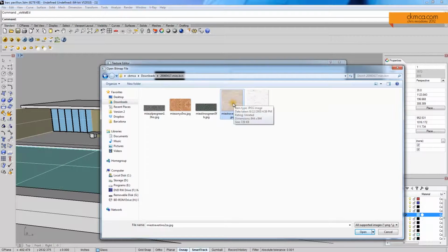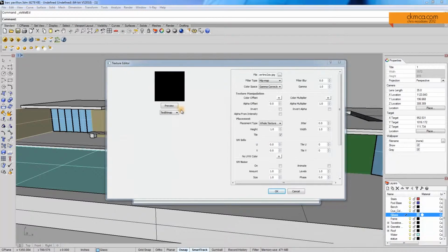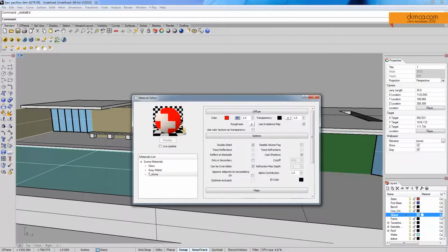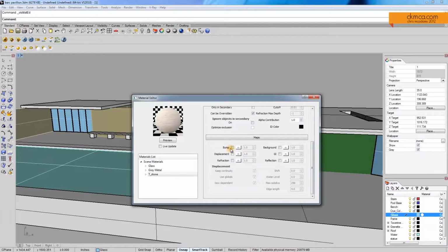So this is the diffuse map, and then we have a bump map. With the diffuse map, I'm going to pull it in, and we can see it's kind of a tannish stone floor, like we'd expect. And now when I preview this material, it's no longer red. We're using this map. The next thing we want to do is to put in the bump map part of it. The stone is not perfectly smooth and flat. It has some flakes to it. It has some ups and downs.